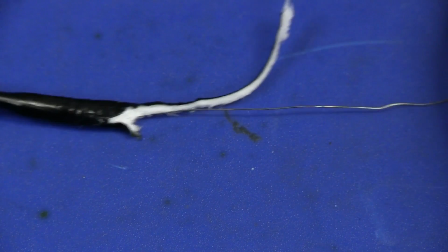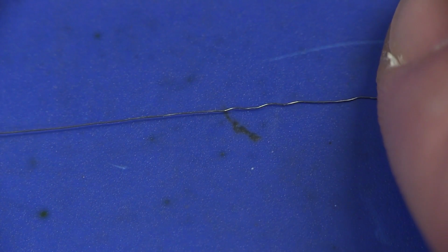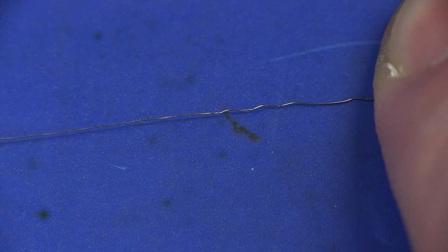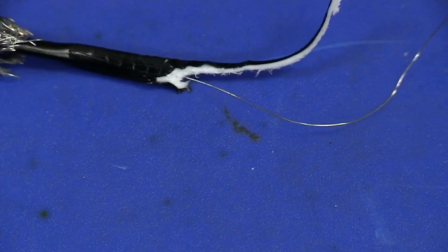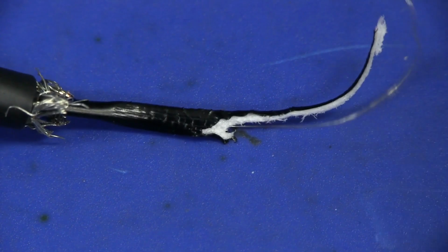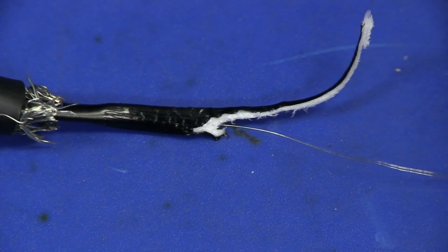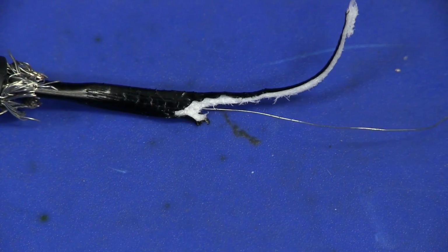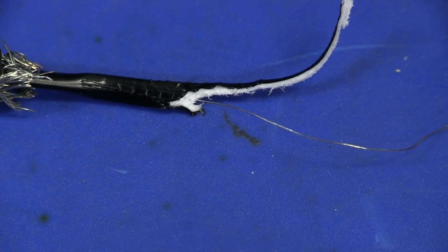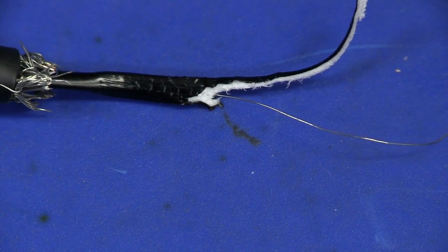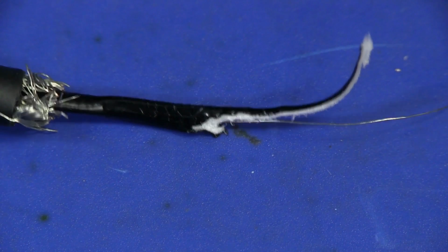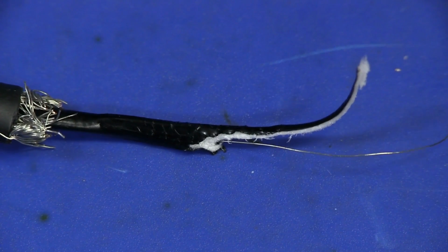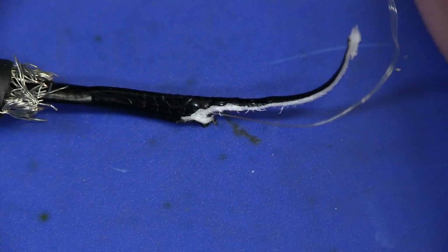So I stripped a bit more of that out, and you can see somewhere along here the crinkled nature of that wire. There it is. See, it's sort of crinkled, and some of your more high performance ones are much more crinkled than that, and presumably they do that to help with the flexibility of the cable. And of course, you'd have to take all that into account for the final resistance, because this is not just regular wire, of course. It is resistance wire, which has a certain specific high resistance designed to match the compensation networks, and that's how the whole probe is able to get its high performance.